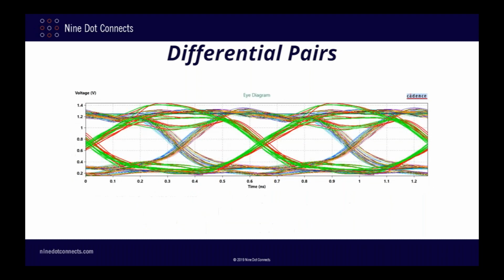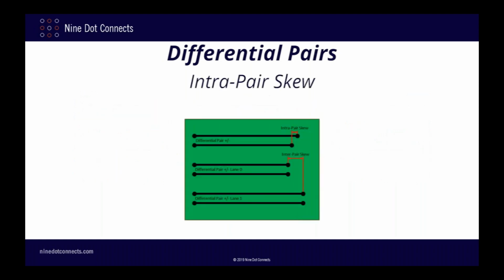Here is the eye diagram view in which I've added back in the data bus signals to provide our eye. We can see that there is some shift in the strobes where the red traces move to the right a bit. However, as I mentioned before, it doesn't seem to be all that much worse, and certainly doesn't seem like it would fail the design. So what's the big deal? Why are we told to keep the length so close, sometimes even to 5 mils or less? It's not affecting the timing much, so why worry about it?